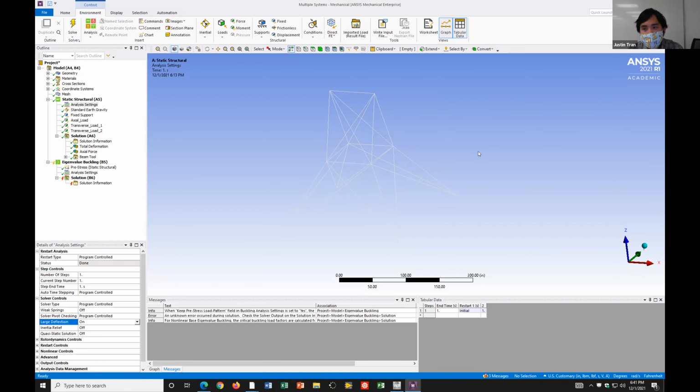Oh, okay, so the locations of the deformation, like the red spots, that is true? That's true, yes. But the actual amount that it deforms, that's not true. So you actually need to do a harmonic response in order to see that. Okay. Awesome. Thank you, Professor. Yep.